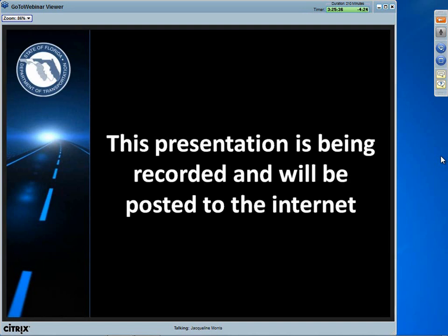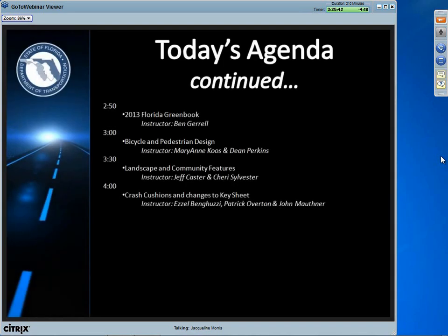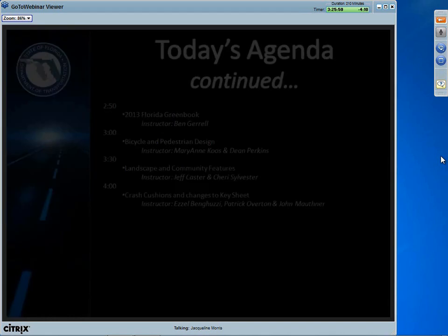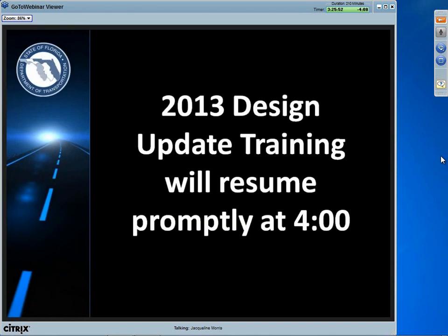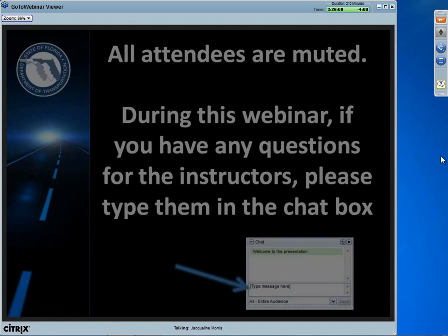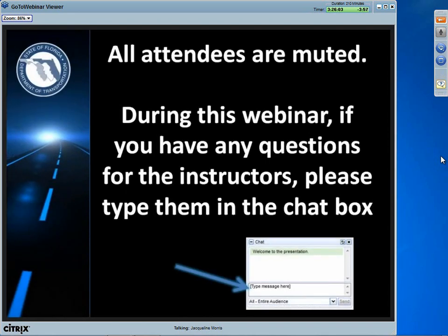Then the next question is, is it necessary to connect a bike lane with a shared use path? No. Well, maybe this is a yes or no. One is that your shared use path should always have a separation from the roadway. So it's going to be very hard to connect this facility, the shared use path, which is supposed to be away from the roadway, to the bike lane, which is adjacent to your travel lanes.